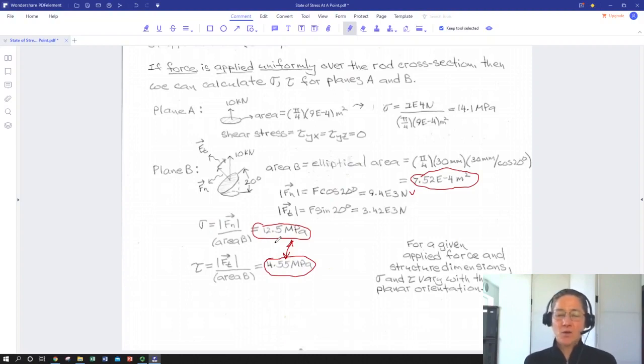That's one example. In certain materials, there are directions in which it is easiest to yield. And so understanding the direction of maximum shear gives us a way to relate to whether or not a material will yield. So that is actually a criterion of whether something is going to deform plastically rather than elastically.